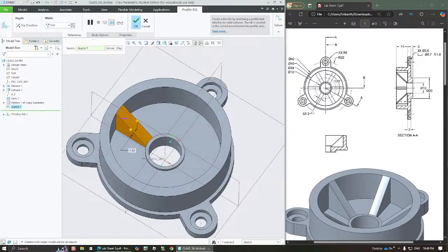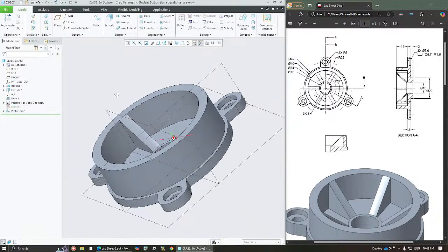Now we see here this is 6 times and the thickness is 3. So just make the thickness 3, and we need to make 6 copies of that. We will not make it now. We will just create one rib at this point, and then we will create a pattern of this to create all the 6 copies. So click OK, and you can see the rib has been created.